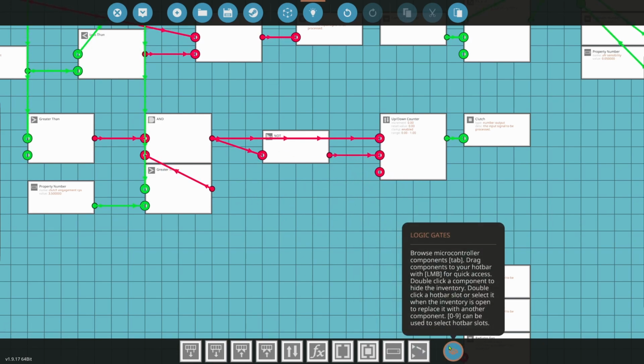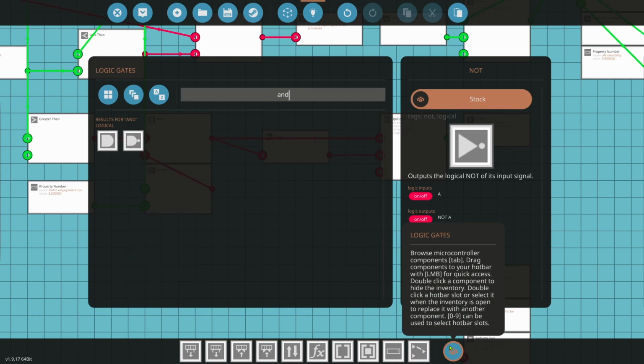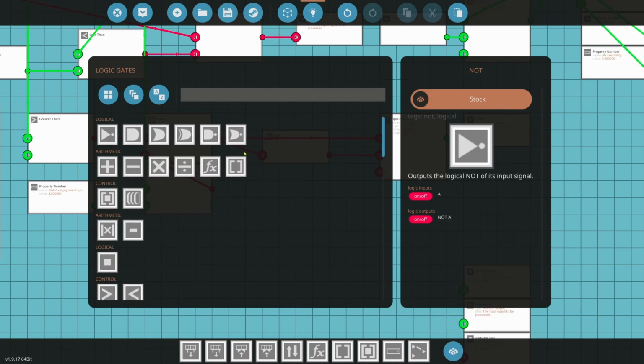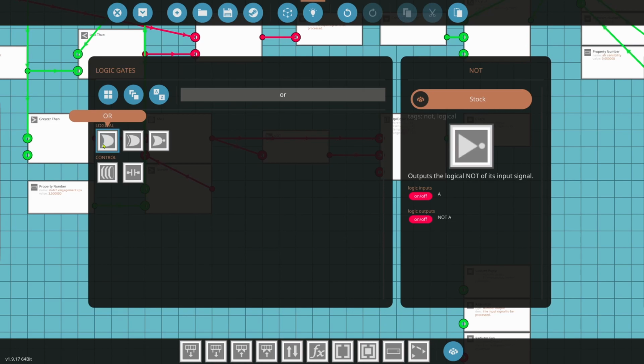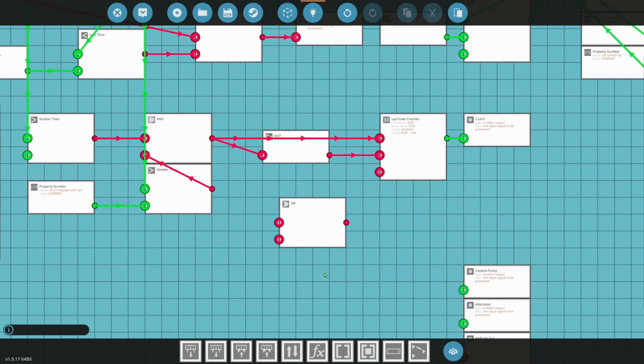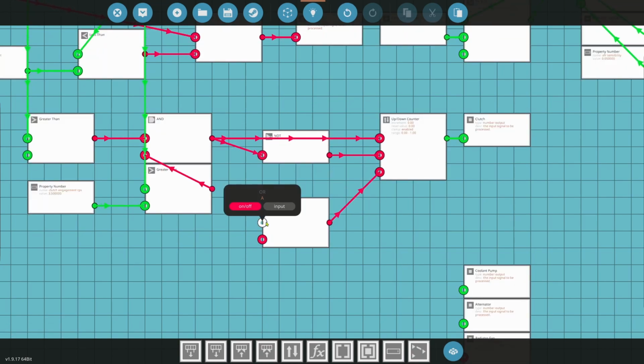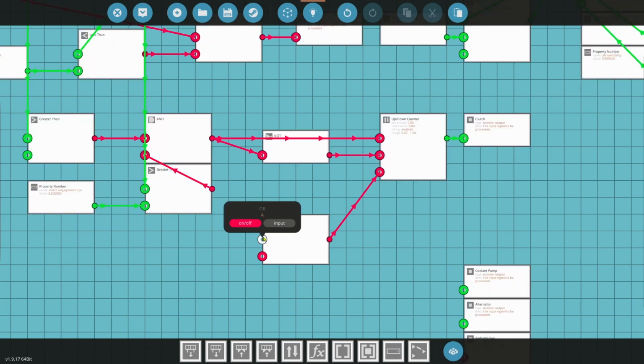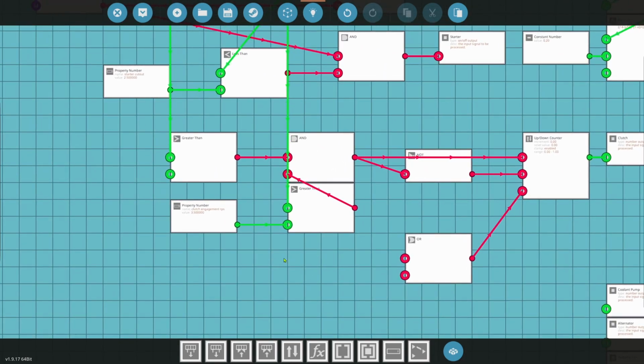But what we'll do is a quick AND. We'll actually do an OR, I'm sorry. So you can do this OR block. This one has 2 conditions. If we need more, we'll do a Boolean. And so we'll leave it as an OR, because one of these conditions would be if our transmission is in neutral. So you plug your neutral value into here. And the other condition is if your clutch goes below a certain value. You don't want the engine to stall, all right?